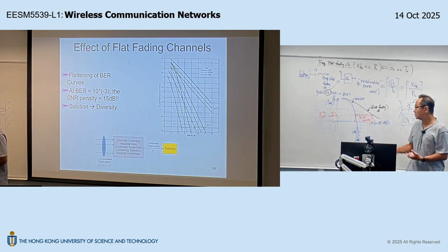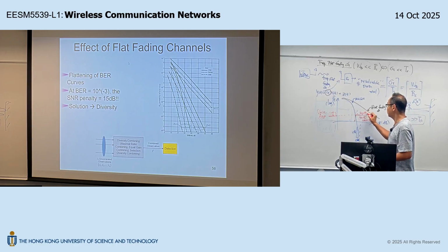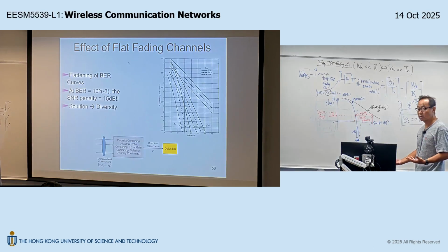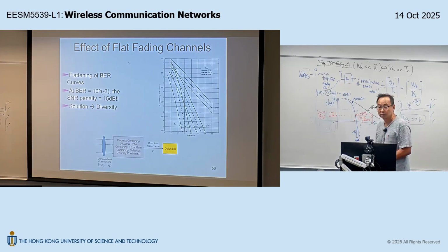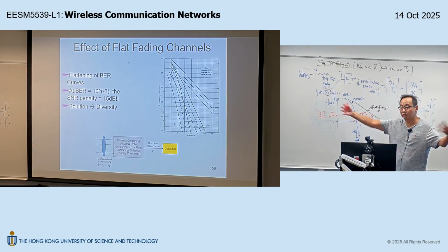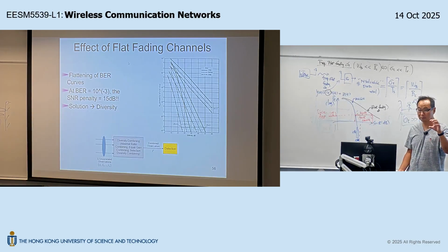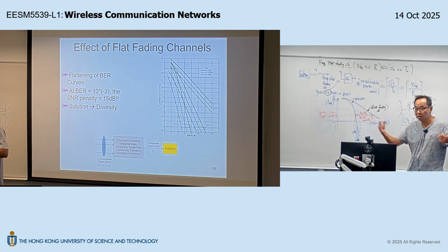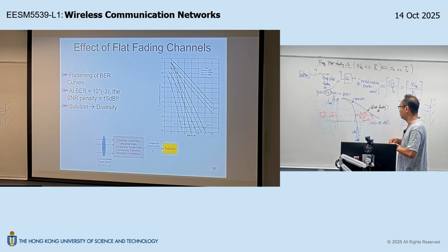It's a penalty, right? So let's say if this is, I don't know, 20 dB. What does that mean? In the context of a cellular operator, in order for me to maintain the same coverage as before, I need to increase the power amplifier by 20 dB more power, if I can, to keep the same range. Or if I cannot change the power amplifier, I need to take away 20 dB from my link budget. That means my coverage will shrink. Is that okay? So that will be the penalty. Obviously the immediate penalty is coverage.